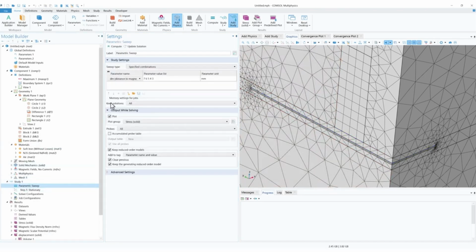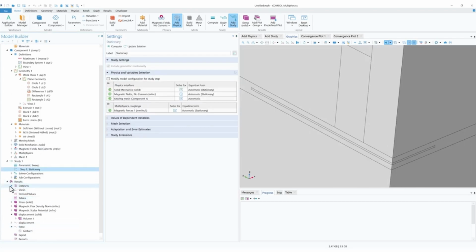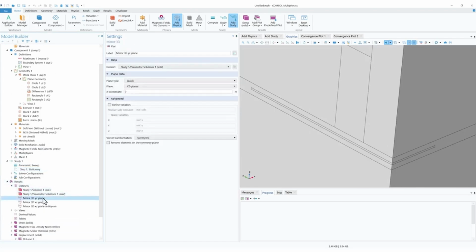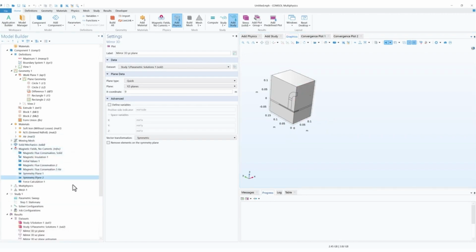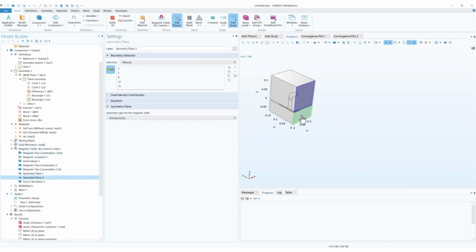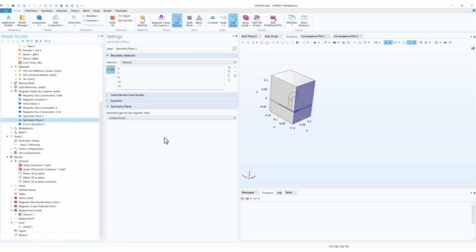And after that, we set up the parametric sweep and solve the model. We got the result, but to make the result more realistic, we mirrored the solution across the 2 sides, and we set up the antisymmetric property due to the effect of the magnetic field here. So here you have to remember that you have to choose antisymmetric if you are making a symmetry on the other side. And then we actually plotted the result, calculated the displacement and the force, and finally we are done.